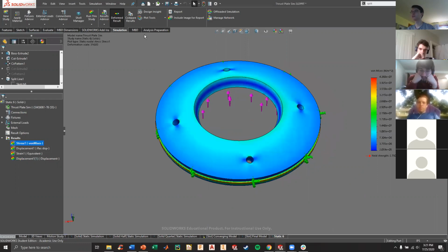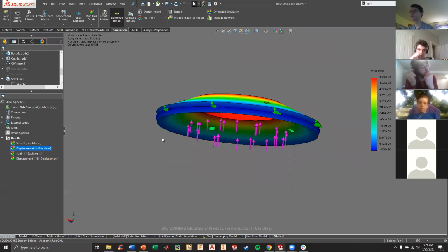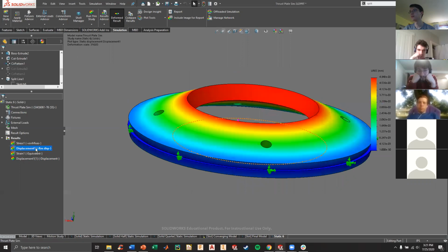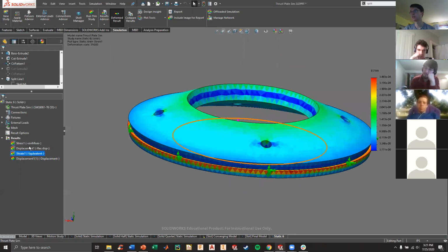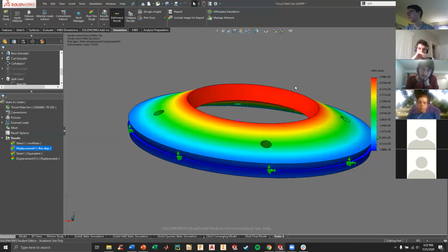A little quirk of how FEA works, and it's more of a fun fact than anything. It only really matters once you get into making it: FEA solves for the displacement of every element in your part. And then from that, you can use material properties. So solving the displacement will look at stuff like the modulus of elasticity of your material. And then to get something like the stress or the strain of your material, it will just do some math there that's not necessarily related to what you would normally consider FEA. So that's a little bit of a fun fact about what FEA is.